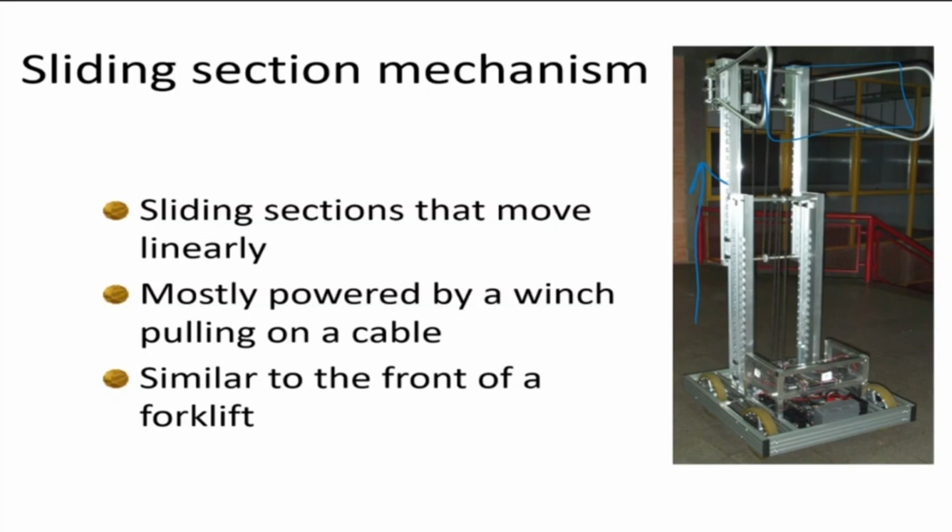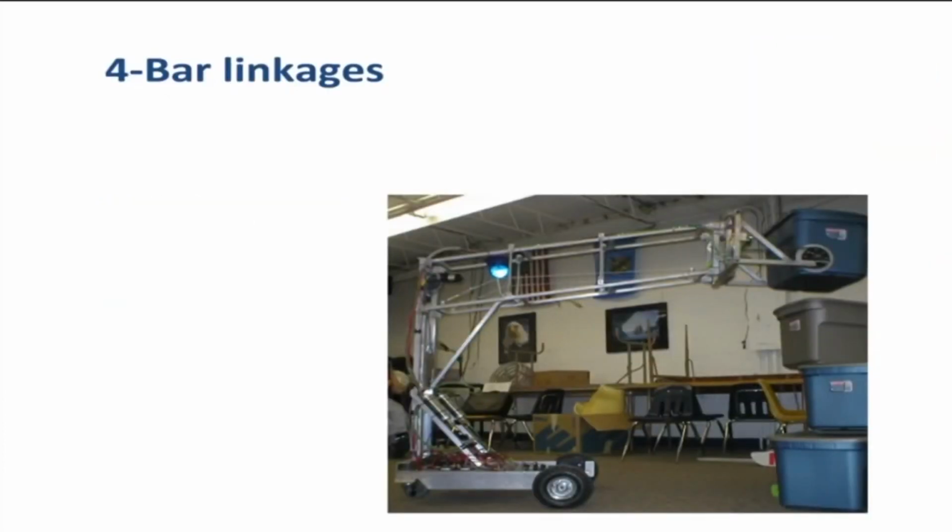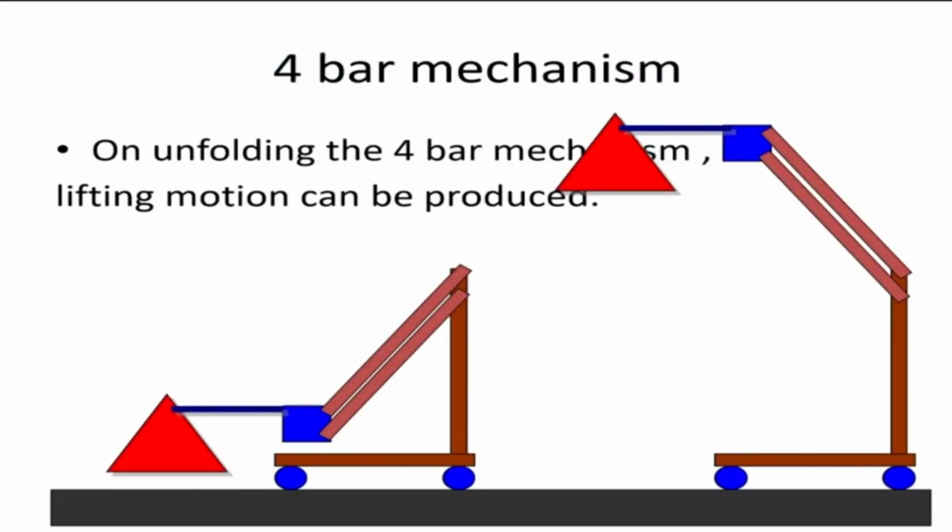And special purpose grippers like the ones shown here for catching soft toys and soft balls for different applications. So there are special purpose grippers which are meant only for catching particular kinds of materials, and the actuation of such grippers can be by means of 4-bar linkages and mechanisms. So there is a 4-bar mechanism, lifting mechanism, which can be fitted onto the end of a robotic arm.